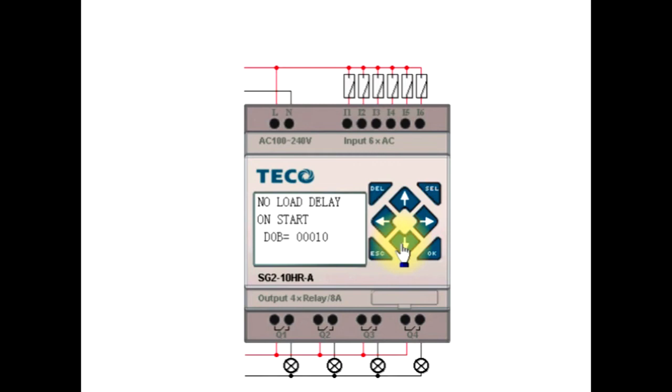The no load alarm is typically not that critical when you're first setting up anyway, because somebody's there, they've got the wand in the Gaylord and they're paying attention to what's going on. We're much more concerned about a Gaylord running empty, hours after the original setup for the no load alarm. So it's currently set at 10 seconds, but you can set that at 120 seconds or 600 seconds, whatever you need for your application.